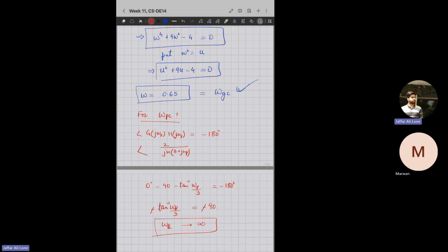So you have questions based on Nyquist stability criteria. We did that in detail. Basically, you need to find the number of encirclements around either minus 1, 0 or 0, 0, the origin. That depends on the mapping of the Nyquist contour to either the GsHs plane or the 1 plus GsHs plane. Accordingly, you decide. In the second case, you need to find N equal to Z minus P, where Z is the closed loop poles and P is the open loop poles.